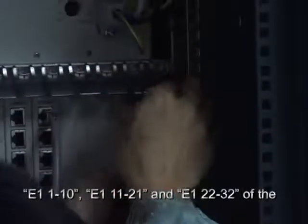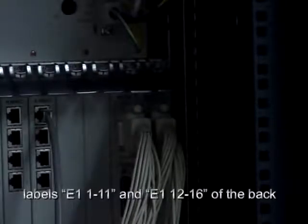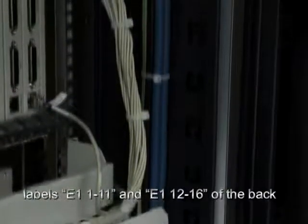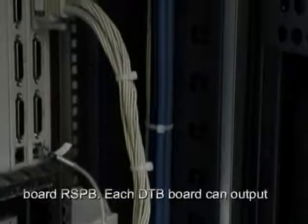End A of the cable is a DB44 plug, which is inserted at the labels E1 1-10, E1 11-21 and E1 22-32 of the backboard RDTB of the DTB board, or the labels E1 1-11 and E1 12-16 of the backboard RSPB.